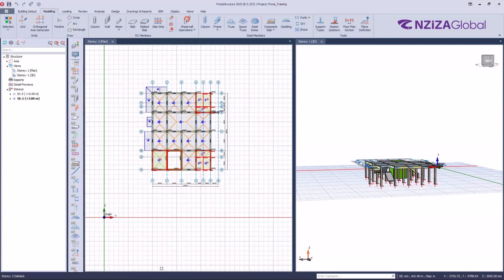So try on your computer, play with these story operations that we have seen: insert story, generate story, delete member in a story, and remove story. Try to work on it for 3 minutes, 5 minutes. Then we will go on with the edit story command.